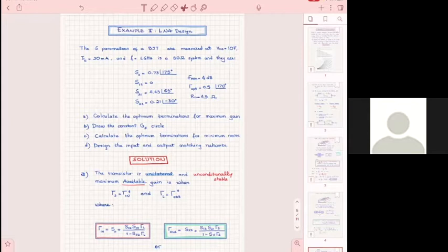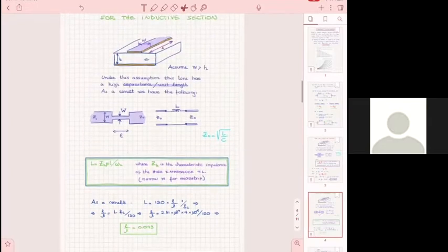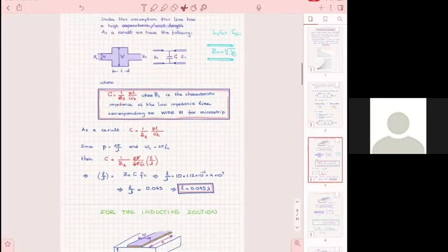In a stepped filter, if you have more L's and more C's, when you do the translation, all of the C's will be different, obviously, all right? They're not all of them going to be the same. They're going to be different, but your low impedance will always be the same. It's just the lengths will be different.